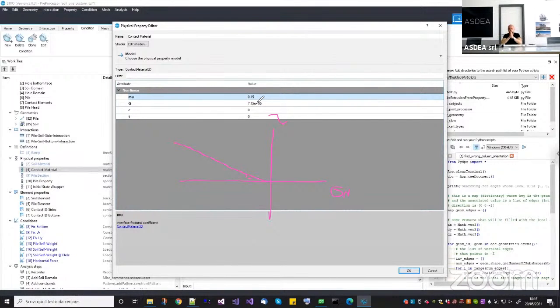Okay, so if you have just a zero length contact interface, it should be a very large value, almost infinite. But if you use a very large value, it will give a lot of convergence problems. Instead, if you want to simulate a cohesive part of material that has a finite stiffness, you can use that one. Then you have C and T.